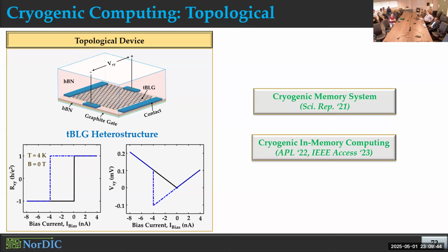But I'm not sure if there is any tool where we can do all this interface level simulation for circuits. But there are TCAD tools, COMSOL tools, which we can use to simulate at the device level and see what happens in the interface. But at the circuit level, we always take the physics understanding from those tools, and we develop compact models, which is some sort of approximation in some cases, and then we do the circuit level analysis.